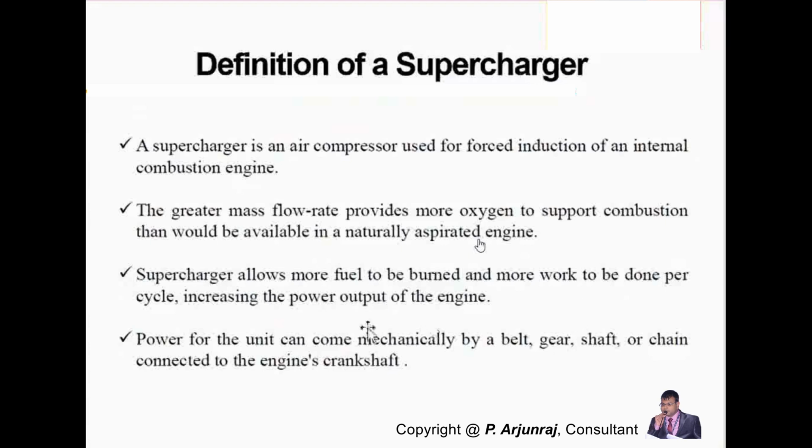And again, you see here, in the case of the supercharger, we are going to get the power mechanically. We are going to use different methods like a belt method, gear system method, shaft method, or a chain connected to the engine crankshaft.